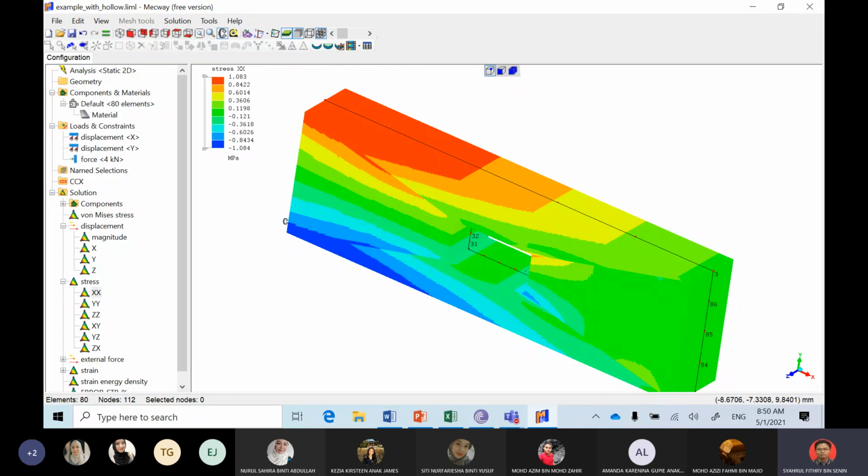And also we have tensile stress here, compression here. This is tension. Sebab dia because this is a cantilever. Cantilever, you must have tension at the top, compression at the bottom lah. But here the stresses is not so big in bending because it's almost 0.019, but you still need to put extra reinforcement but not so much as here.